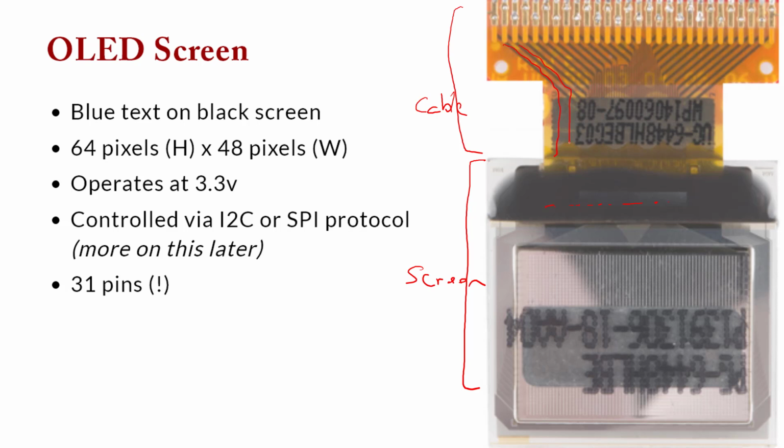Ideally, on the back of your screen, there should be a little stick of kind of like foam glue here, and it flips up and cements to the red breakout board. Ideally, keep that taped back and don't adjust it. I have myself needed to reposition them, and the cable breaks easily, and then the device is basically useless. So just be careful with that.